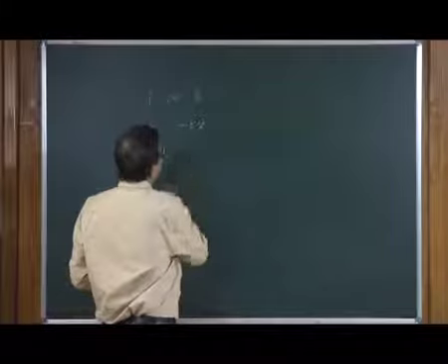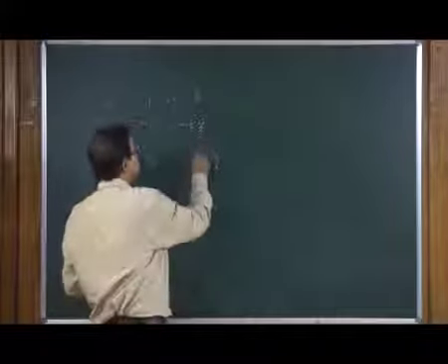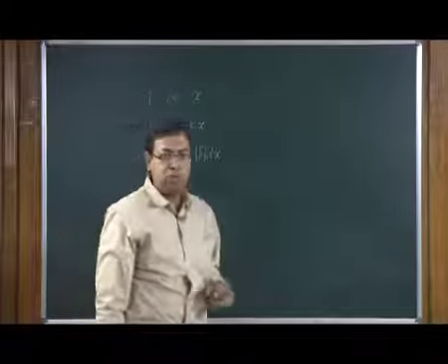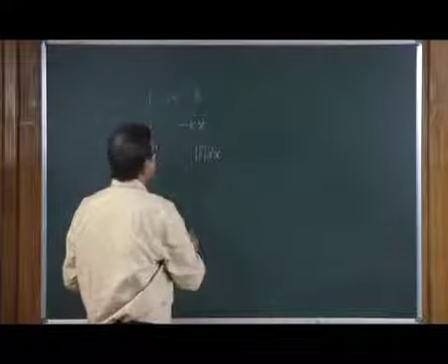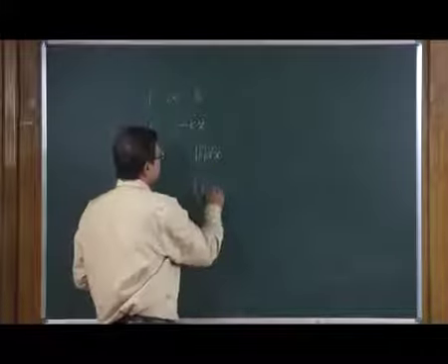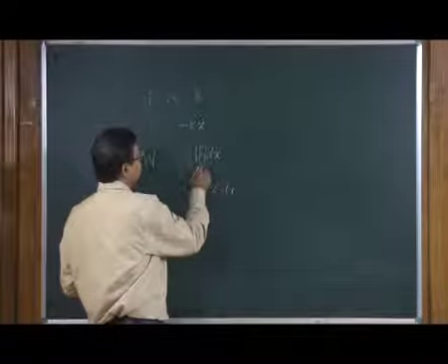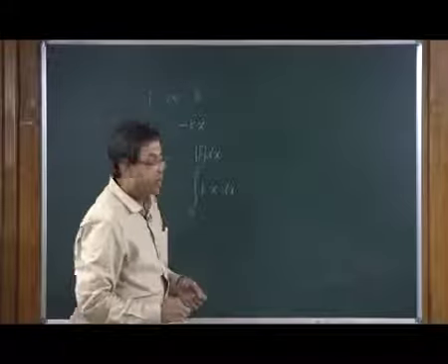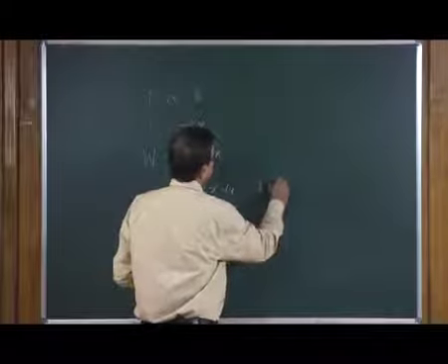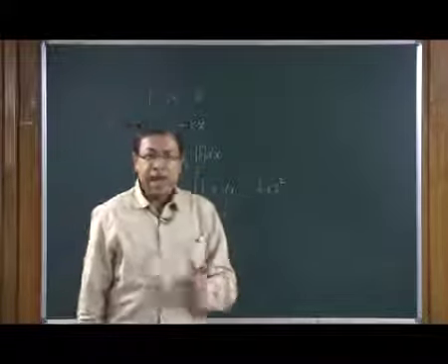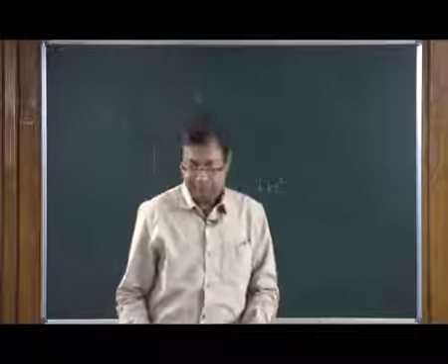So, this will be given by the integral of F dx, and at this moment let me take the magnitude of the force, because we are just going to calculate the magnitude of the work done. This is going to be the integral of kx dx between 0 and some maximum displacement or elongation x, and this is half k x square. So, this is the elastic energy that is stored in the deformed body.